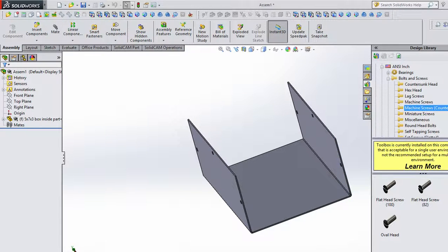100-degree screws, it's a larger angle, and if you have a larger angle, I'll draw this on the board, as opposed to this angle, this dimension of this screw, this height, is smaller. So you can fit that in thinner pieces of sheet metal, as opposed to this one. However, the 82 is really pretty much the standard for just about every screw you're going to find. Just about everyone's an 82. So these hundreds are kind of special order.